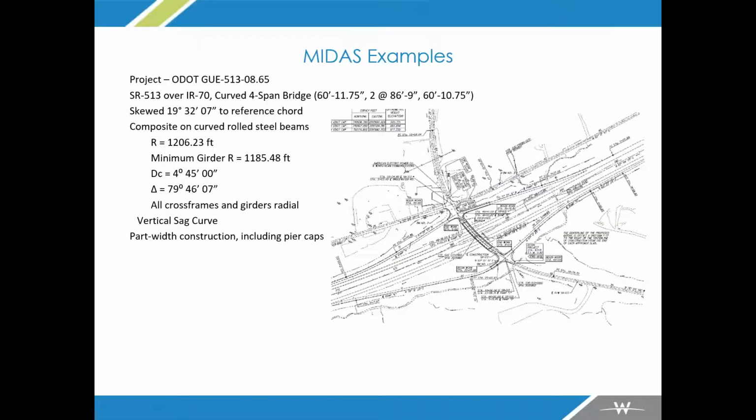This is another project that we used MIDAS for and did the load rating in MIDAS. One of the nice things is that if you do the design in MIDAS, then everything's set up to do the load rating. So, once I've built it once, I don't have to go build another model. I just go to the next tab and do the rating. This one is a little different.